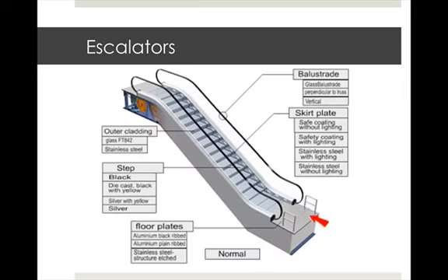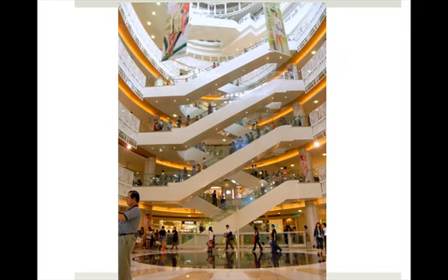Escalators are used as ways to move people faster from one floor to another. Stores love escalators because it allows their clients to see the entire store as they're moving. And in the event of a power failure, they can be used as stairs, whereas an elevator is completely inactive. Now, they are typically not allowed to be part of the official means of egress unless they are enclosed in a fire-rated area. The most common arrangement for escalators is this crisscross format. It's the most efficient way to arrange them.